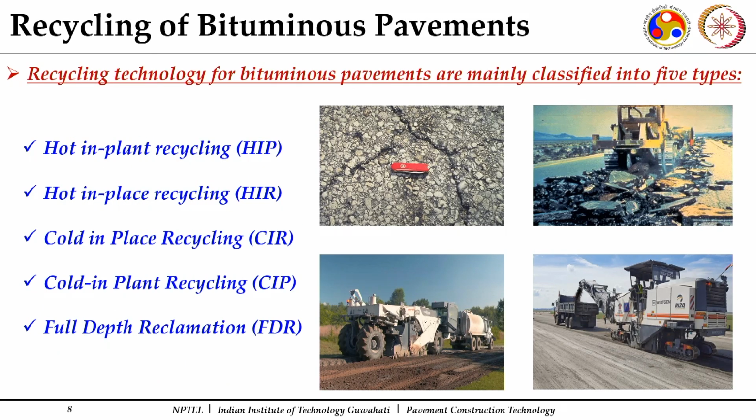Now, the 5 major types of recycling activities or recycling technologies which are quite popular are mentioned here. One is hot in plant recycling; hot in place recycling, as I mentioned, is something done at the site itself, and something done at the plant level is hot in plant recycling. Now, as the term says, hot, so higher temperatures are involved.